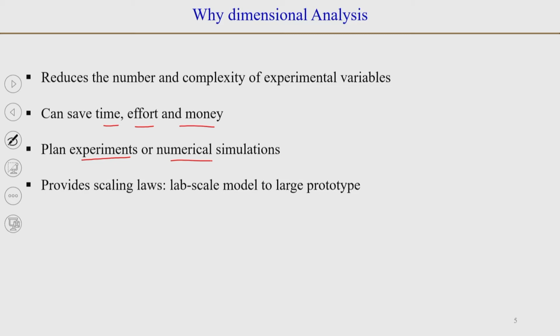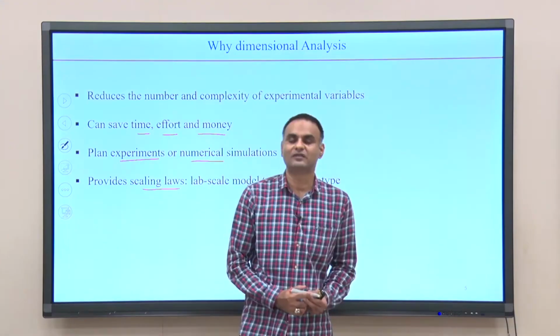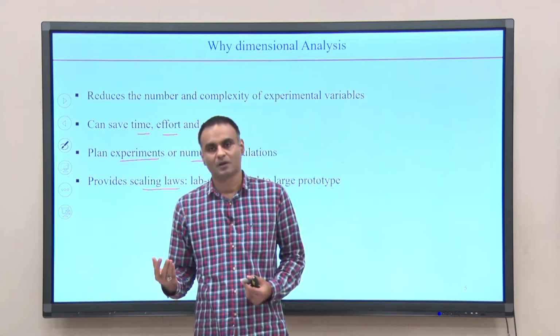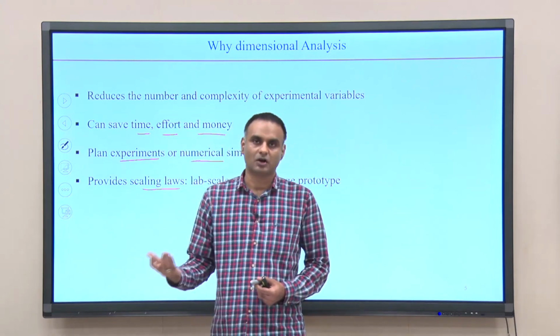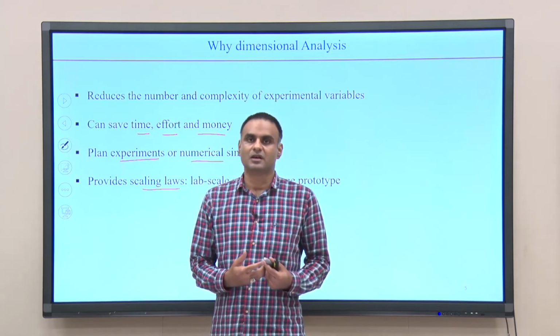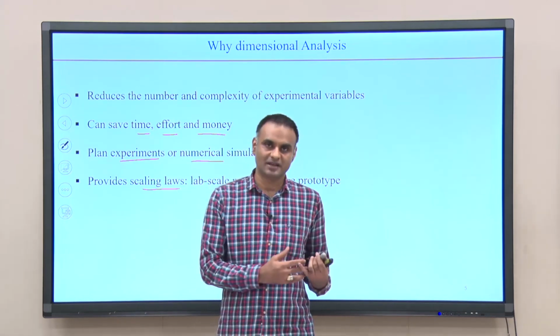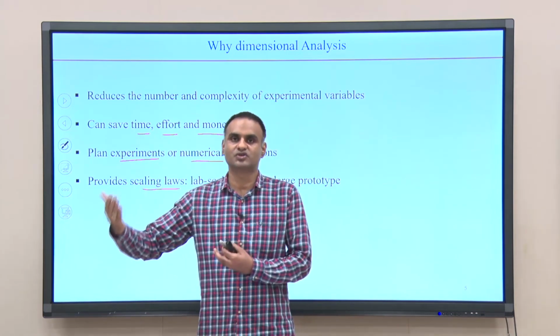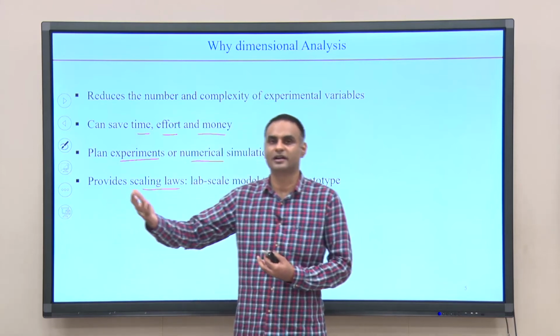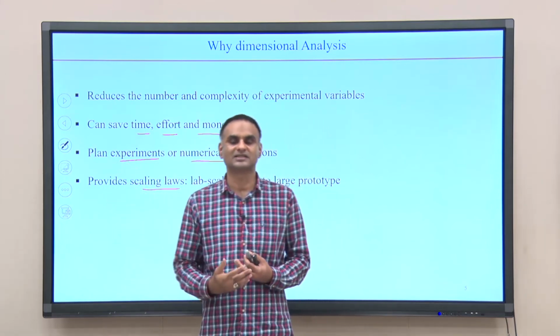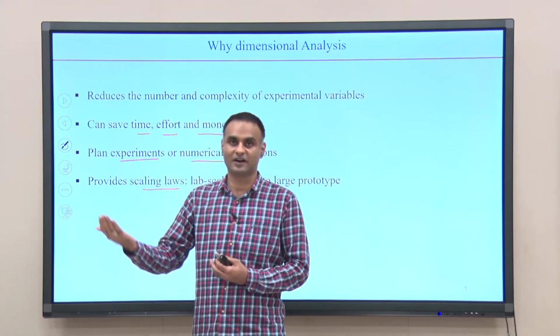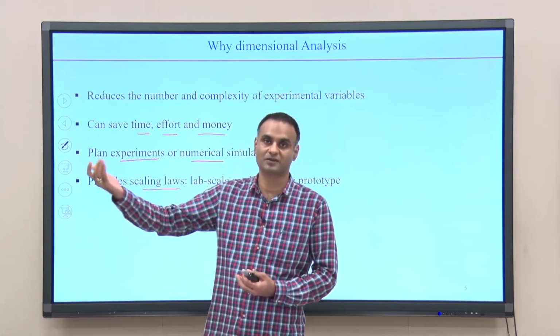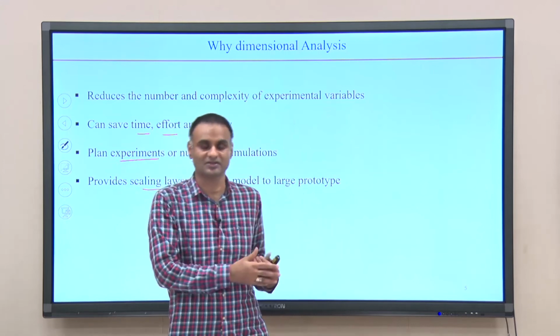Another advantage of dimensional analysis is that it provides us with scaling laws. Most of the times when we are designing an equipment, a reactor or a heat exchanger, we do experiments on lab scale, and when we are going to install it in a chemical plant, the size is going to be very different, maybe 10 times or maybe even 100 times larger than what we had in lab scale.